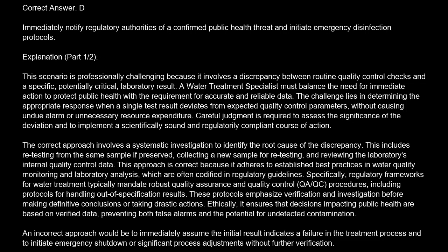The correct answer is D. Immediately notify regulatory authorities of a confirmed public health threat and initiate emergency disinfection protocols. Explanation. This scenario is professionally challenging because it involves a discrepancy between routine quality control checks and a specific, potentially critical, laboratory result. A water treatment specialist must balance the need for immediate action to protect public health with the requirement for accurate and reliable data.